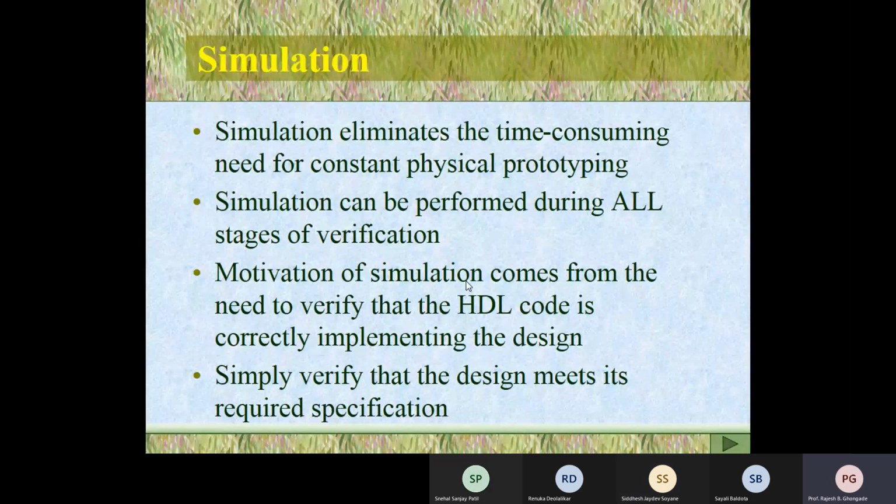What about the output? As somebody had said, 5 volts, but okay, that's all right. Output voltage is one part. Second part is the maximum load current, also called the rated current. This load current requirement comes from the user end. For example, a customer wants to drive a circuit which demands a maximum of 1 ampere. So he will say my maximum load current is going to be 1 ampere. So this is one specification: 5 volts, 1 ampere.